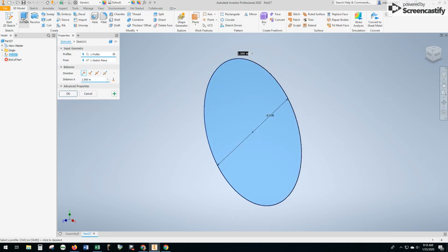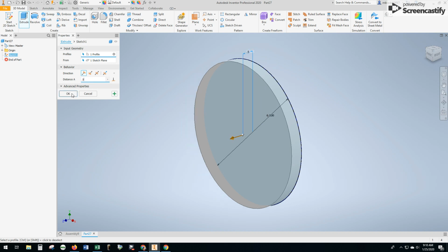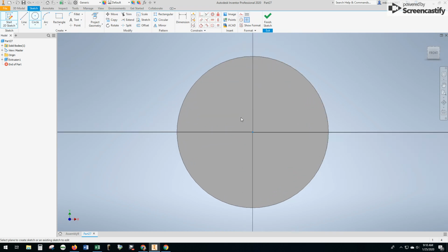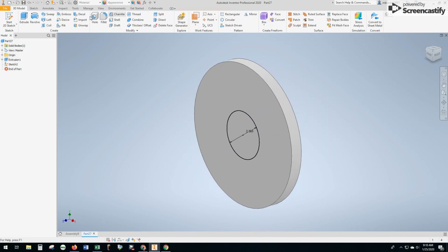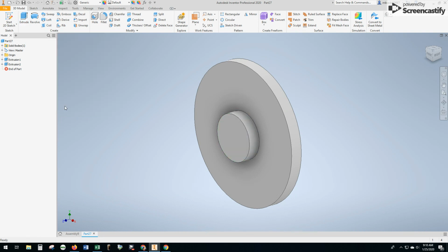All right, and I'm going to extrude that. Instead of 1 inch, I'm going to change this to 0.5. Okay, so it's a 1/2 inch thick. All right, now I want to add to this. I want to build upon it. So I'm going to click the Start 2D Sketch button, click on this front face, and stick with the circle tool. Again, I'm going to work from the origin, and I'm going to click and pull my mouse out and type in 2, enter, finish sketch, and I'm going to extrude that now. 1/2 inch is good, so I click OK.